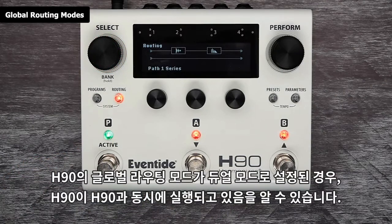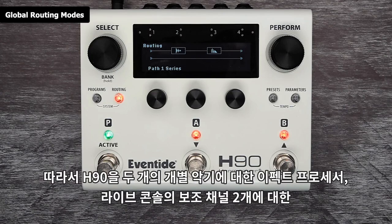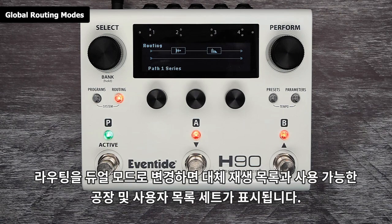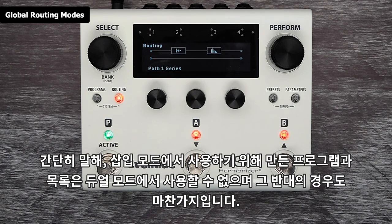When the H90's global routing mode is set to dual mode, we can work with two independent signal paths at once. This makes it possible to use the H90 as an effects processor for two separate instruments, as an outboard effects processor for two auxiliary channels of a live console, an outboard effects processor on two stereo sends of a DAW, or for using the 4-cable method in a guitar rig. Note that when we change our routing to dual mode, an alternate playlist and set of available factory and user lists will be enabled. To put it simply, programs and lists we create to be used with insert mode cannot be used in dual mode and vice versa.